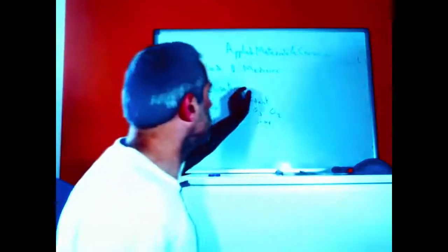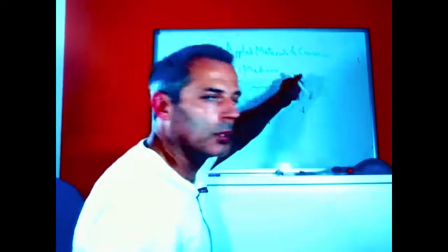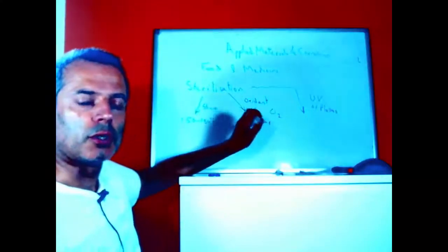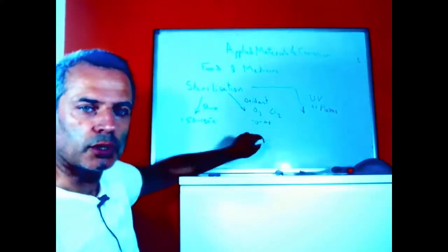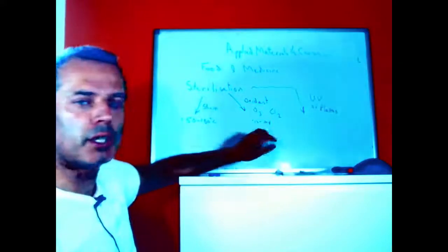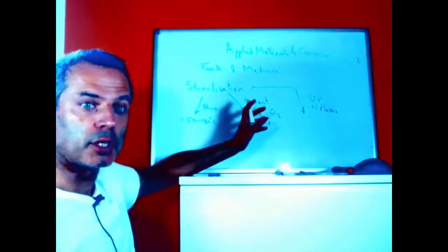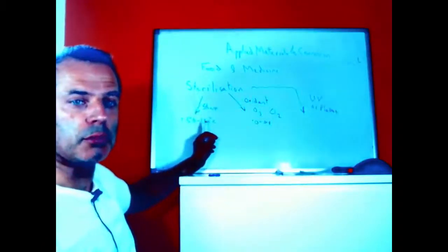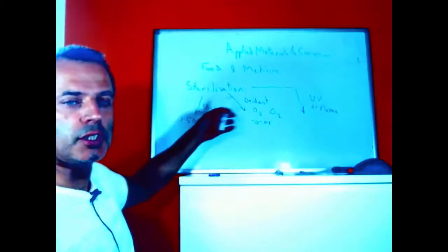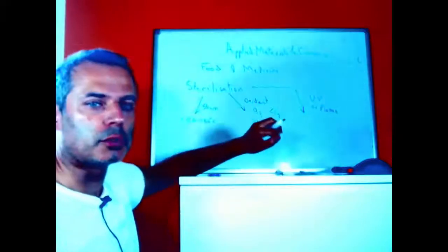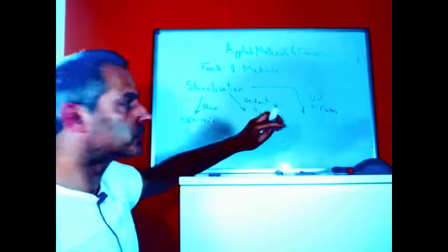We could also use energy directly, so we could use light, UV, or plasma. That gives all of our materials a starting problem. So if we take any polymer that can hydrolyze, polyester for example, it's going to have trouble in steam. If we take cellulose, steam is going to degrade it fairly quickly, not super quickly. We can treat cellulose with steam, but it will degrade.